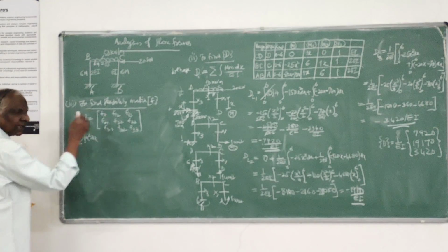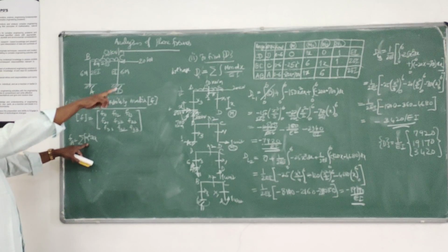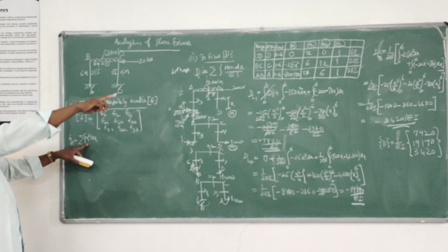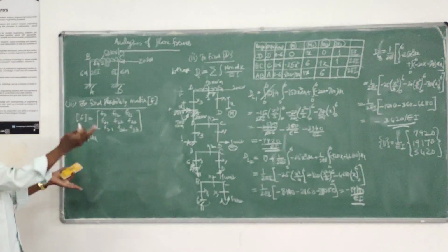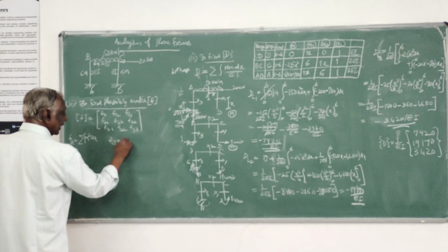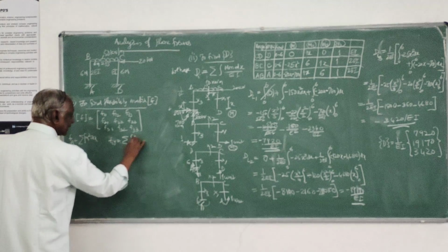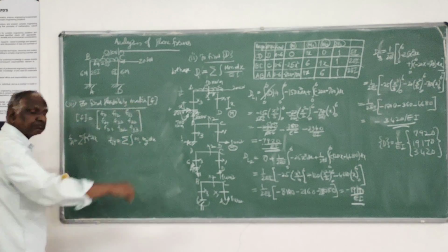All these diagonal elements you can find out by taking the square of that unit load matrix, whatever you have done. Then the product, that is Fij, you can work out as sigma of integral mi mj dx.